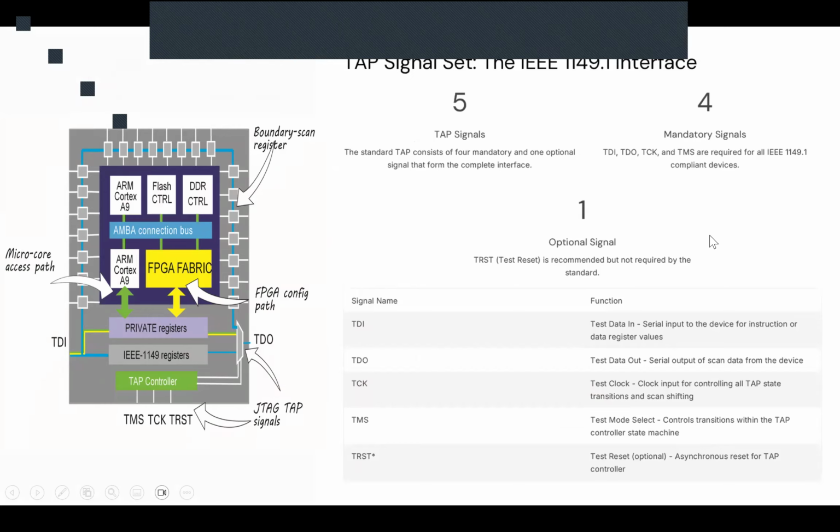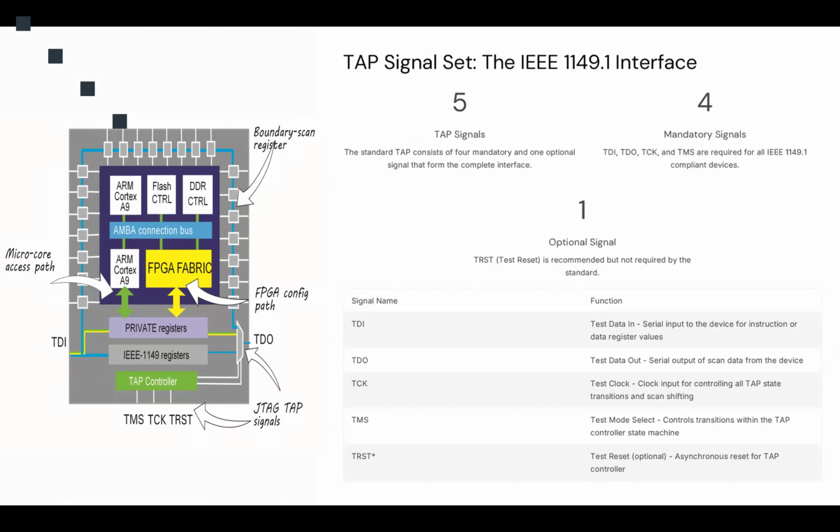We talked about the different aspects of that boundary scan control. We mentioned some of the test access port, TAP, signals. We mentioned the TAP controller. We mentioned the clock, which we showed with TCK, the TAP clock or test clock.